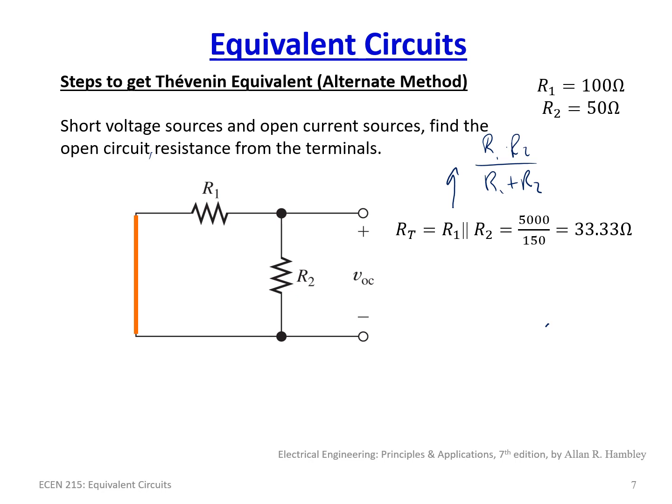And this all comes from the equation. Remember, the master equation for this is just 1 over R1 plus 1 over R2. And if this is resistors in parallel, technically it's 1 over R1 through 1 over Rn, equal to 1 over R equivalent. And that's where we're getting this. So now that we have that, we now have RT.